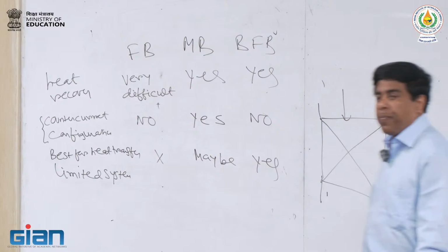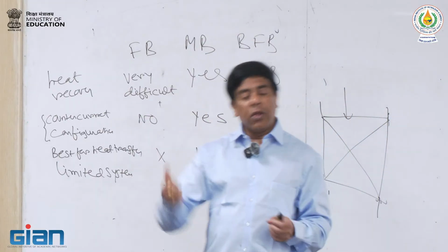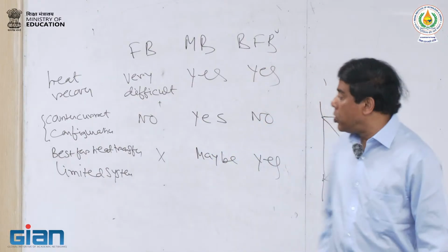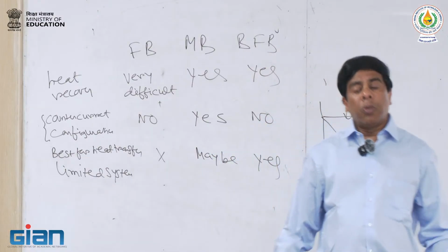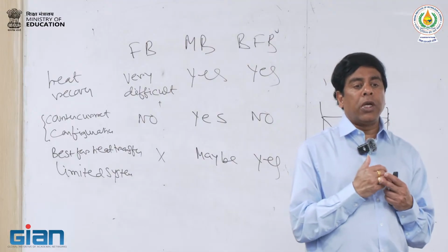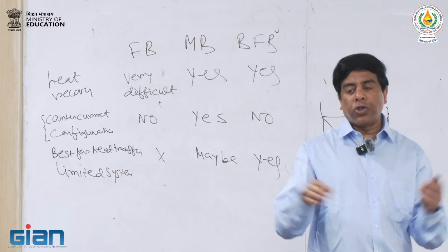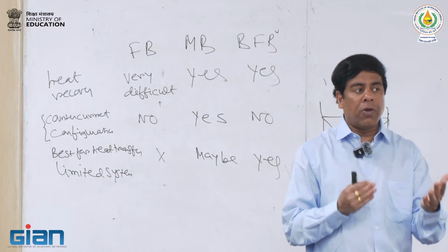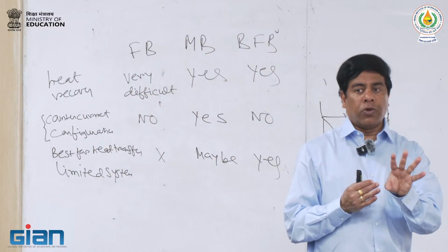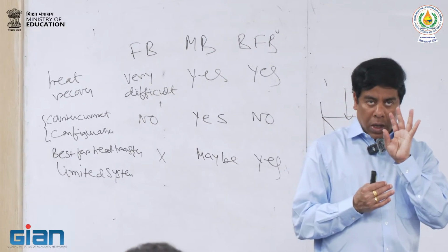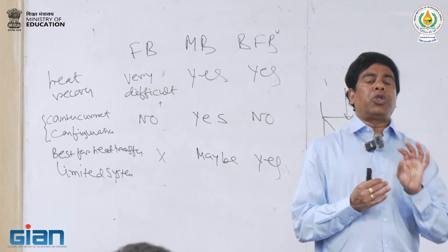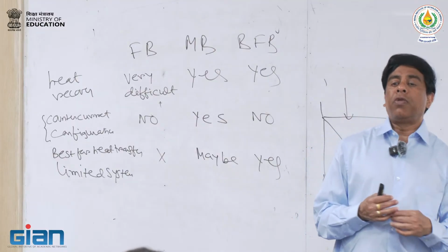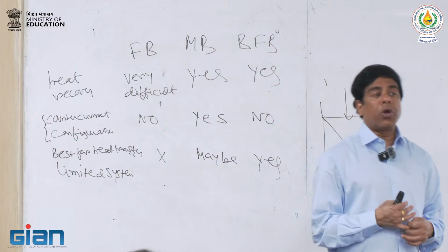And for mass transfer, I will not write anything, because it depends upon where the mass transfer shows up. If it is within the particle level, then using the fluidized bed will not help you. If it is on the bulk side, then the moving bed or the fluidized bed can help. The issue with the fluidized bed is that the driving force is completely gone. It's the difference between the CSTR and PFR. So you lose the driving force.